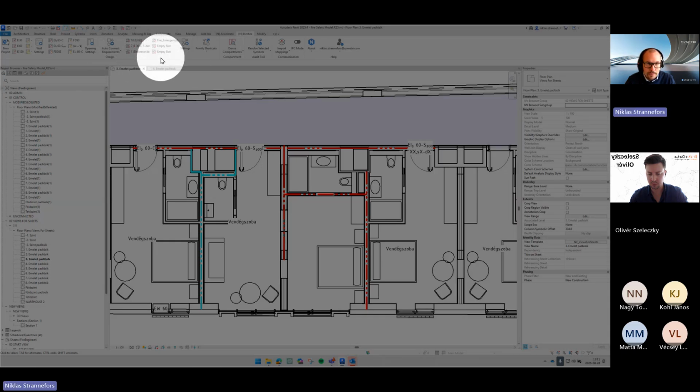The next 6 slots that I'm going to mention, which we have here, say empty slots for you guys. You see number 10, 7, 1, and emergency something. The numbering that you can see is from the Danish compartmentation, or sorry, the Danish template. But here we can add requirements that we want to add even more onto our model. So for instance, in those regions where we don't use a text but a symbol to place requirements, we can use these to place opening requirements. But we can as well use these to actually start placing door requirements, such as one-handed openings, such as 179 handles, or two-handed openings requirement, door magnets, whatnot.